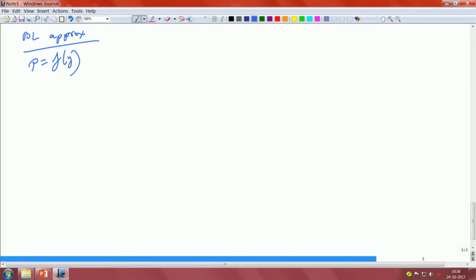Remember our flat plate boundary layer, there of course the axes were a little bit different. Okay. But based on that you get what I am talking about. y scales as h, that is the height, x scales as delta t, right, and dP/dy equals dP∞/dy equals minus rho∞ g. So, it is essentially hydrostatic in origin, got it. So, P is only a function of y, that it has to be, right, because P is not a function of x.